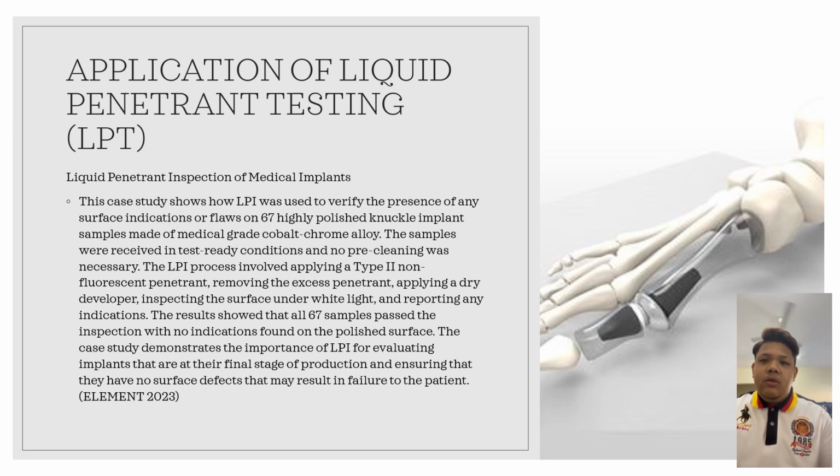Next, I would like to present about the application of liquid penetrant testing, the liquid penetrant inspection of medical implants. Now this is what we call a case study. We got it from a journal that we researched. This case study shows how LPT was used to verify the presence of any surface indications of flaws on 67 highly polished knuckle implant samples made of medical grade cobalt chrome alloy.